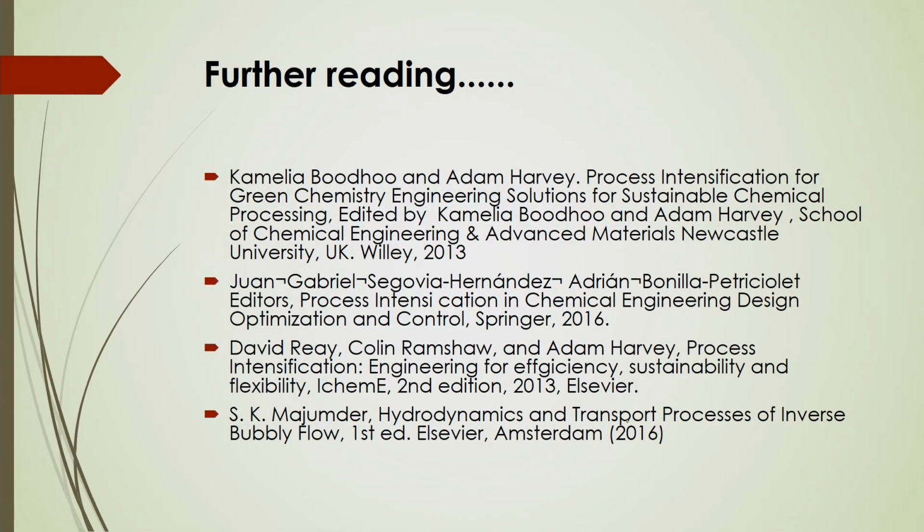So, I think we have learned something about the process intensification mechanisms based on the reactive environment: how it can be done, how the reduction of back mixing will help the reactive system, how to reduce the limitations of equilibrium, and how we can control the residence time of the phases and also the mixing characteristics.